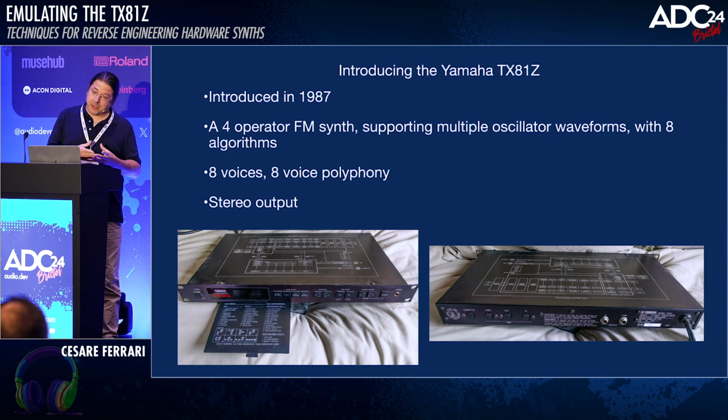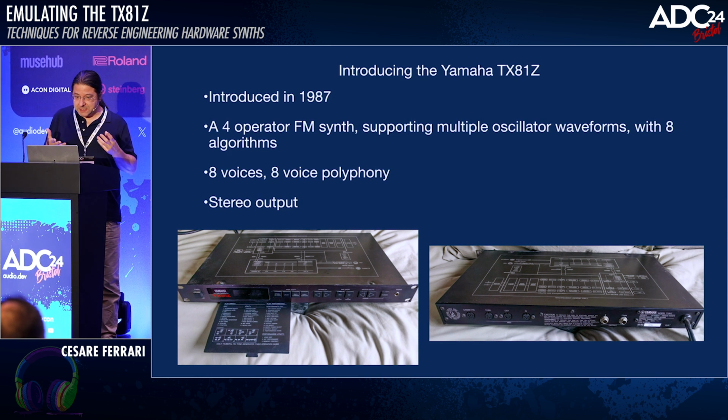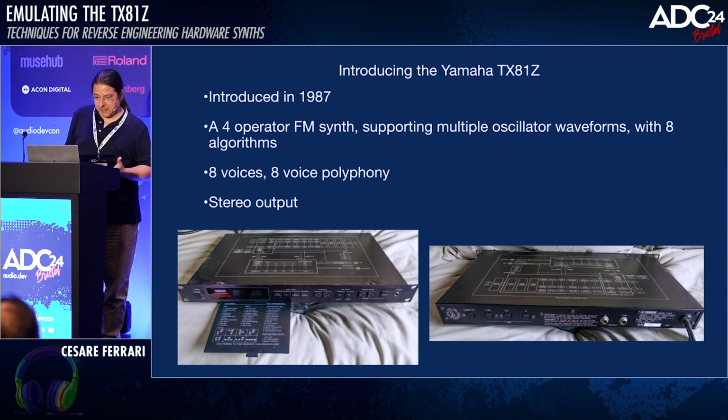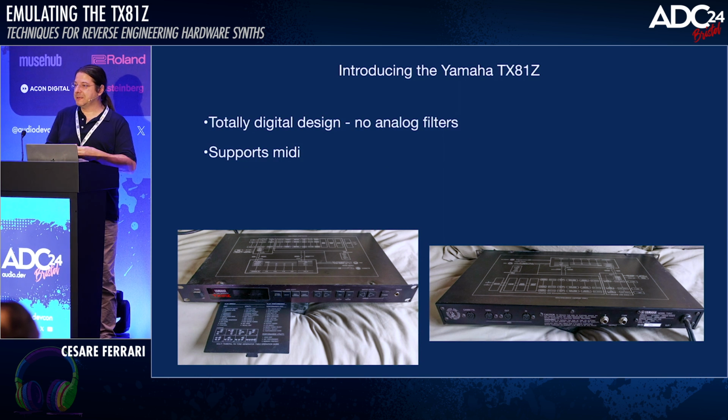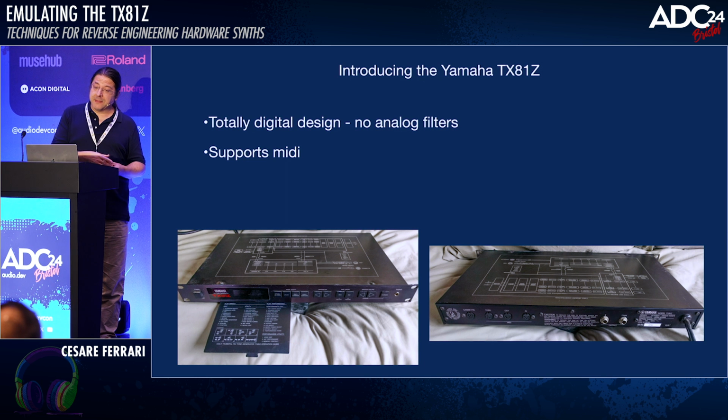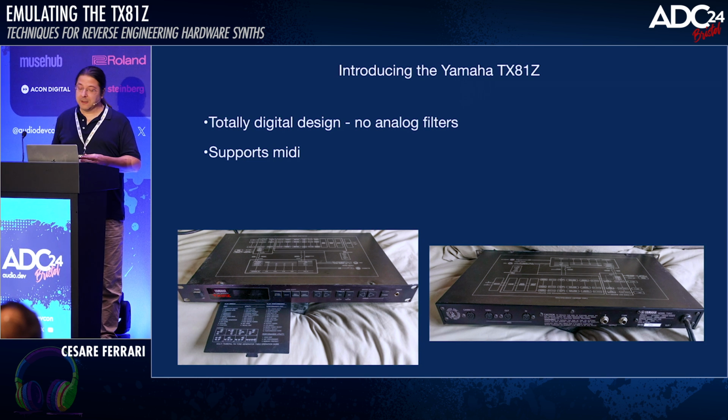It's a four-operator synth, 8 voices. And here's a picture of it. It's got stereo output, which is exciting and novel. It's digital. There is nothing analog in this design, in the sense that all of the DSP, all of the processing, is done in the digital domain, and then there's a DAC at the end that converts it to analog. Although we'll come into some interesting details about that later on.